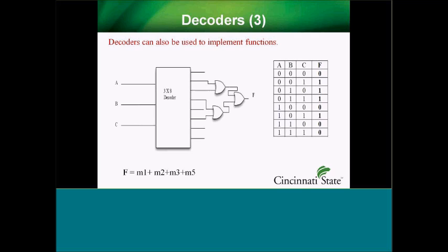They have a conceptual difficulty with this at first, but once you really lay out exactly what's going on, then they think this is the best thing in the world, because all you do is throw a bunch of OR gates on there, and that's it. I do tell them that I don't want you to put all this through one big 4 input OR gate and put it out, because that's not a realistic gate. So I try to emphasize doing everything with 2 input gates, just because that's very standard and makes them think a little bit about signal routing and stuff. But using decoders in this fashion is very, very straightforward.